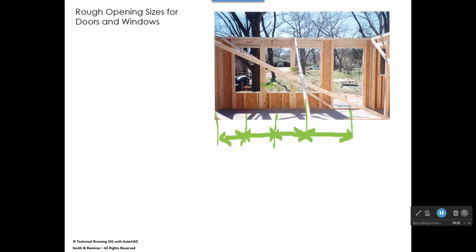Now, another thing you have to keep in mind when you're framing and looking at things like this: if this is the front door for this building, when you walk in the front door, what would be right here on the left of this door? Well, it would be electrical switches, probably for a porch light and maybe for an overhead light in this room, or a ceiling fan or something like that. If you're the designer, you want to take into account that you have enough room to mount all of those electrical switches. And remember, each of those switches will have an electrical box attached to it.